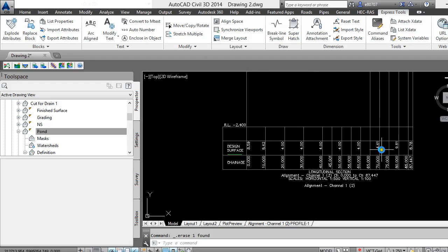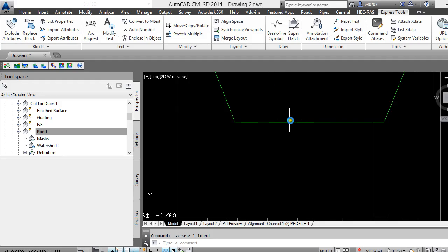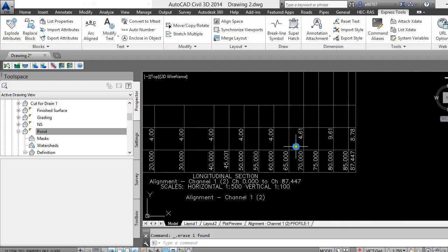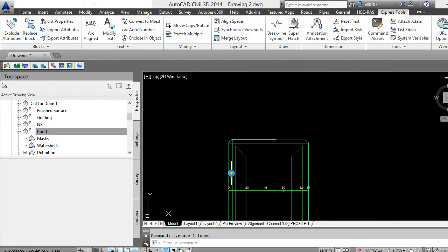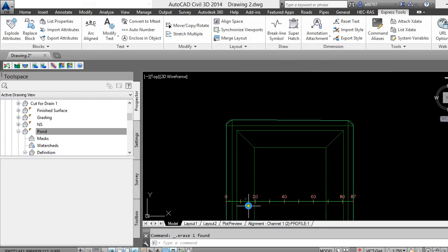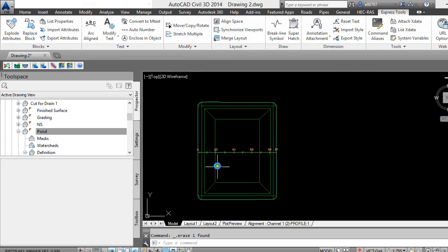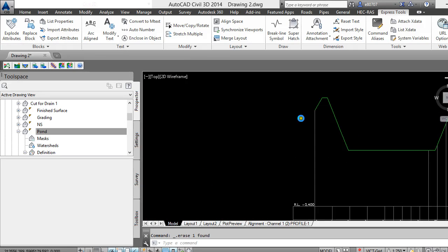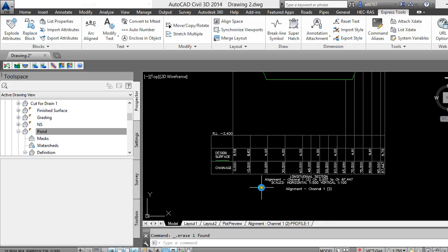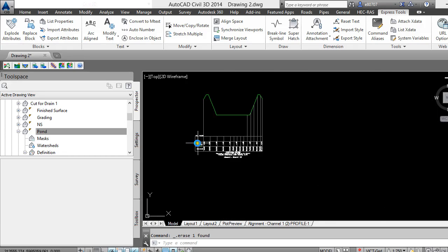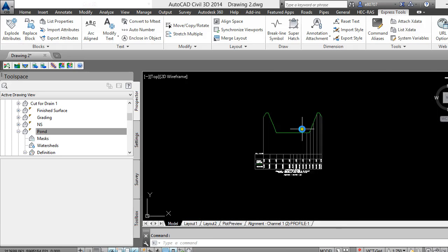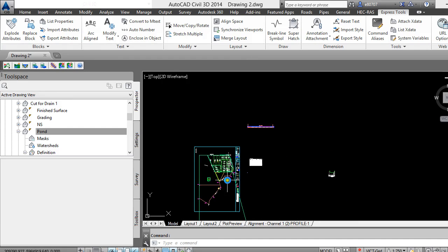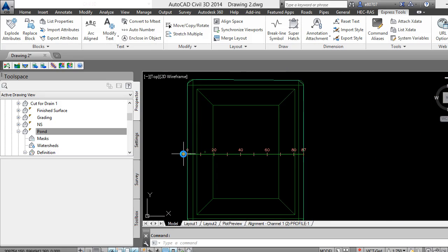So this is your, the 4 is a bed elevation which we created, and then all this elevation goes up there. You can grade it from here as well by creating a little bit of slope in here if you like. Depends how you want to create it, but this is just a presentation of how we're going to cut the road, put it in a profile view, and then basically use grading and feature line.